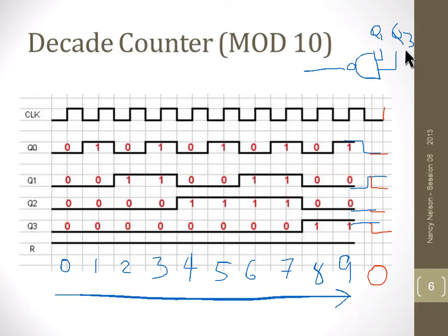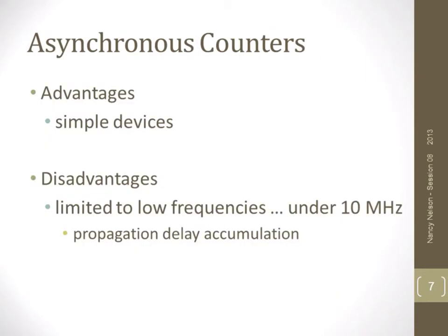So the addition of this nice little circuit allows us to count up to 9 and reset when we get to 10. We can count up to 6 and reset when we get to that. We can create a mod N counter for whatever we would like.